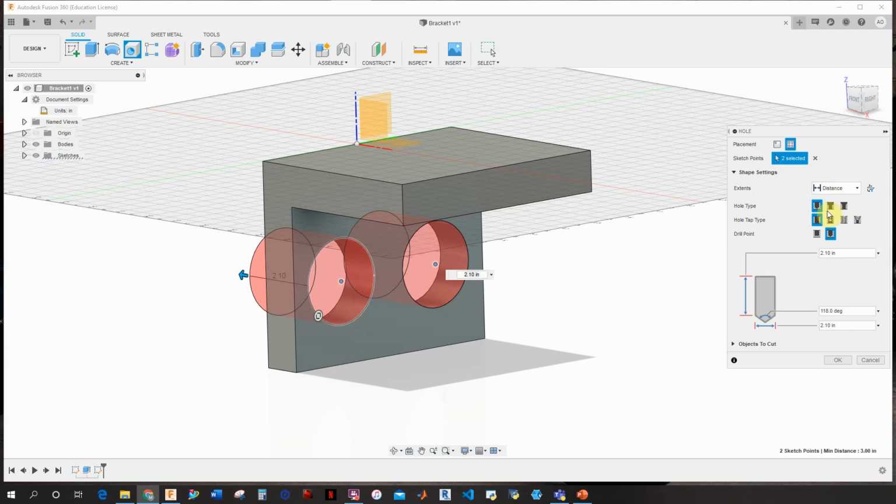Those two types, you will usually see when people are machining. Sometimes for the holes they want to do a counterbore or countersink. That's usually to allow the bolts or screws to remain flush with the surface, while still allowing for that extra surface to apply pressure downward. In this case, we're going to do a countersink type of hole, but we're still going to adjust some of the values here, and then we'll see what happens.